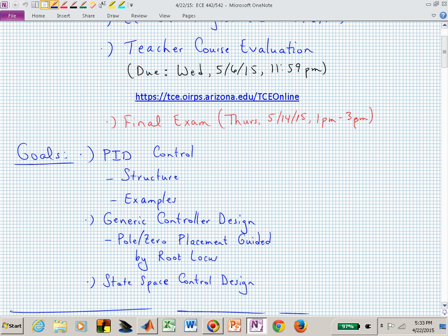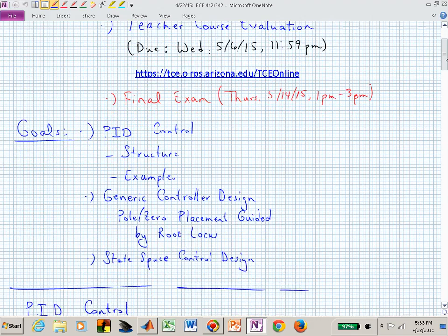But if we were thinking in terms of a transfer function for a controller, then the denominator order needs to be greater than or equal to the numerator order. That's when we're speaking about a system and not a signal. So yes, it depends on what we're speaking of when we say causal, in terms of behavior or description.